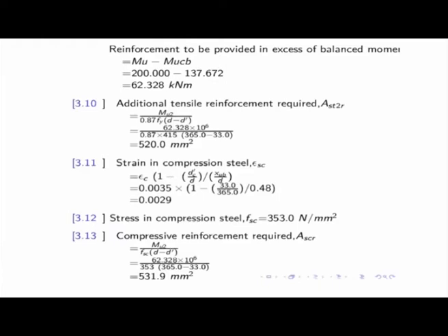Let us say you are using 32 millimeter dia bar. Then 25 millimeter will not be the governing one. In that case, the gap between two bars you have to provide is 32 millimeter. This is the way we find it. Generally we provide 12 millimeter minimum bar, but you have to accommodate those bars within the space given to you, within the width of the beam. I hope now I am clear to you.